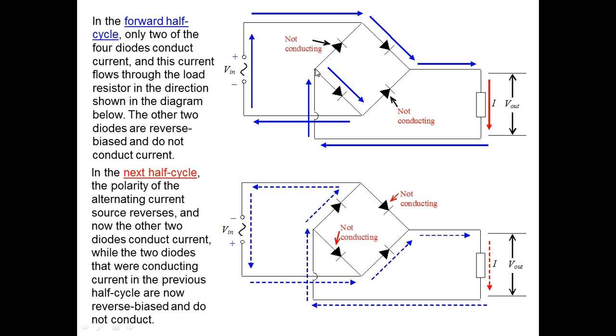At this point, there are actually two diodes pointing in the direction that it can move. However, after passing through the resistor on the right, the output resistor, the potential at this point will be lower than it was before. Hence, there's only one direction that it can go, which is downwards, then to the left and back up again.